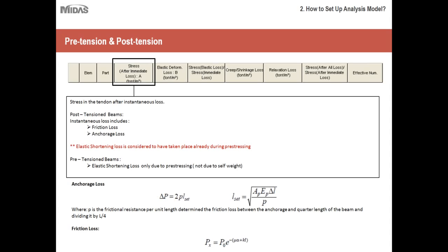Depending upon the type of tensioning you are applying, whether it is pre-tension or post-tension, there will be different types of losses. So it is sometimes really hard for any software program or for engineers to consider these losses separately. What they do is either they just lose track that it was a pre-tension tendon strand, and they compute the post-tension tendon losses. So there's a lot of scope for human error that keeps all the engineers on their heels.